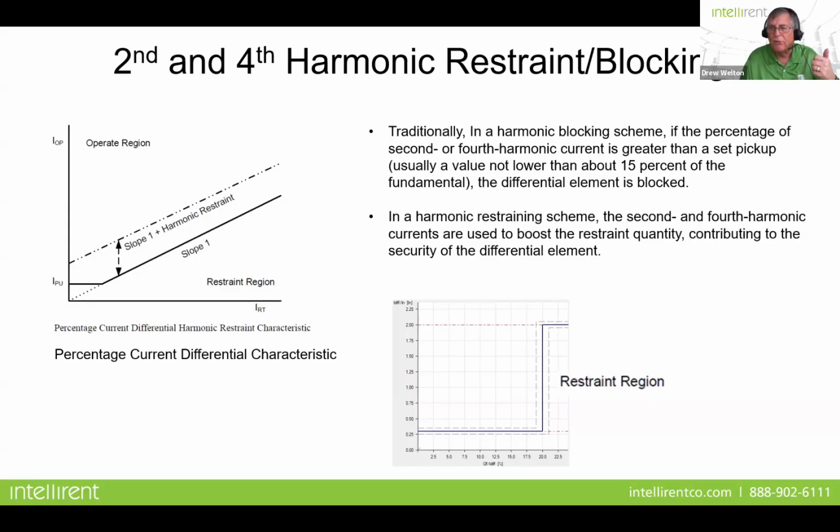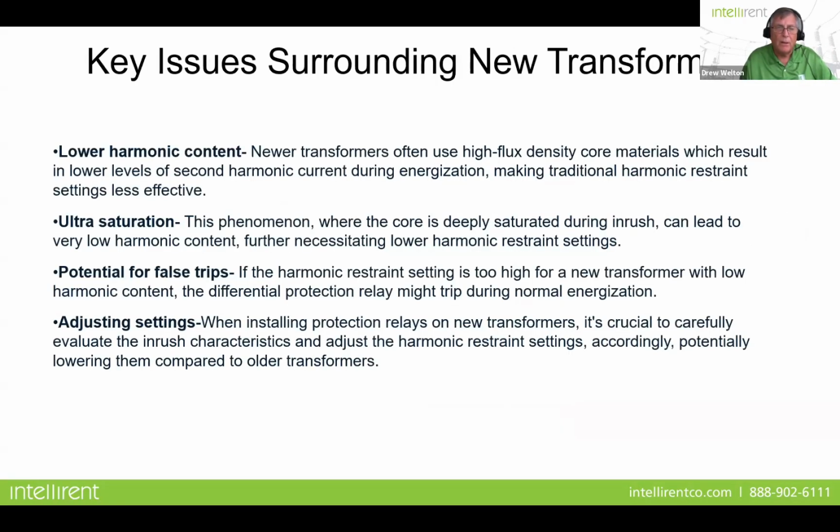So both second and fourth, typically I see just second enabled. If you want to add some more stability to it, you can do both second and fourth harmonic restraint as well. So there's some key issues surrounding new transformers because some of the new materials in our newer transformers